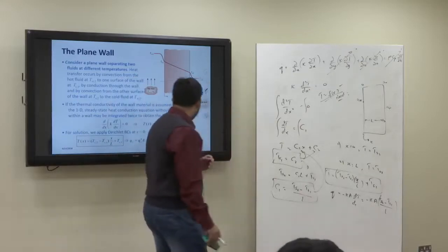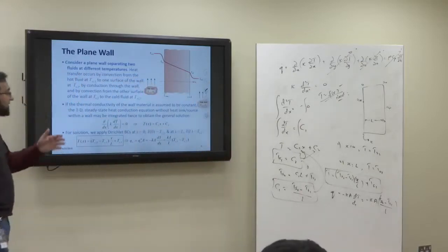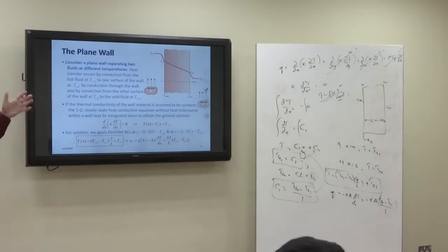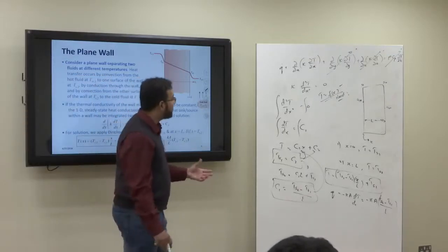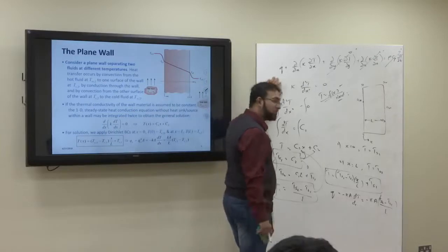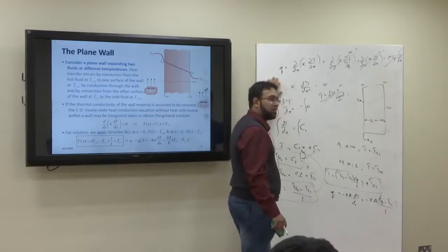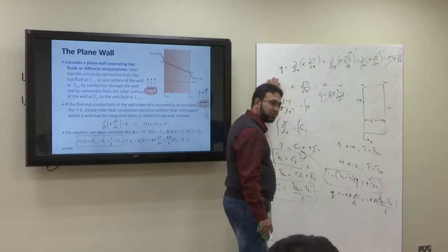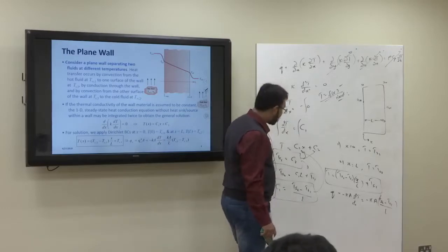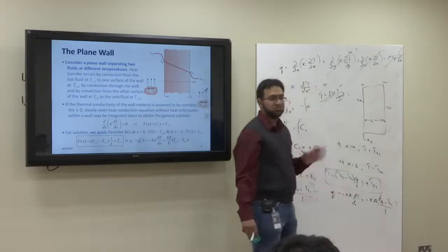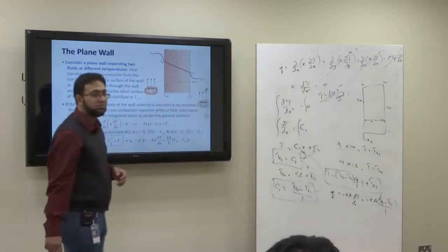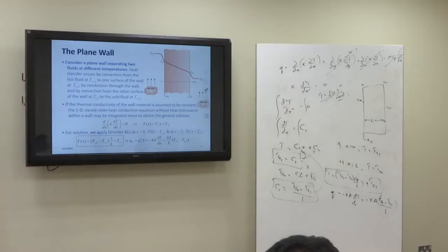But anyways, first of all, do you understand this? This is a very simple and very beginning small proof derivation type of thing, where we used it for a plane wall with no internal heat generation, one-dimensional steady state heat conduction. And we come up with this temperature distribution, and based on this temperature distribution, this is the heat transfer. Always ask about the temperature distribution. So questions will become more.